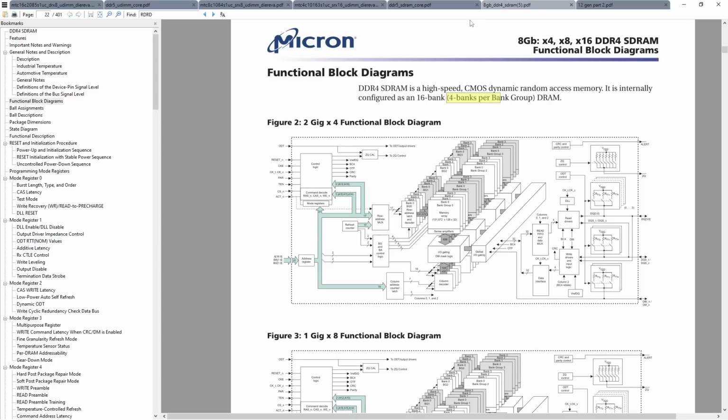It's actually very similar to what happens when you go from dual rank DDR4 to quad rank DDR4, which basically is the same difference. You go from having 8 bank groups across 2 memory ranks to having 16 bank groups across 4 memory ranks. But going from 8 bank groups to 16, you are already basically maxing out the available data transfers on the data bus with the dual rank configuration. So going from dual rank to quad rank doesn't really give you any more performance per clock because there isn't a bunch of wasted clock cycles any longer. Whereas in a single rank configuration, you have a lot of wasted clock cycles.